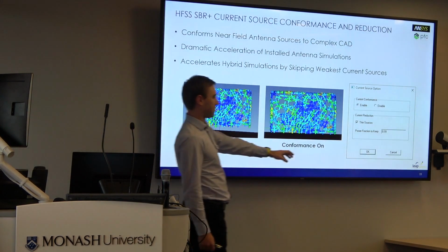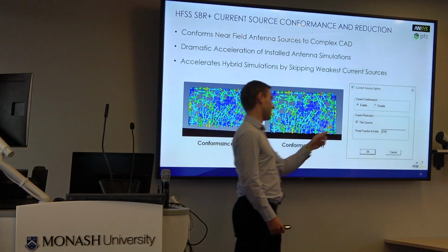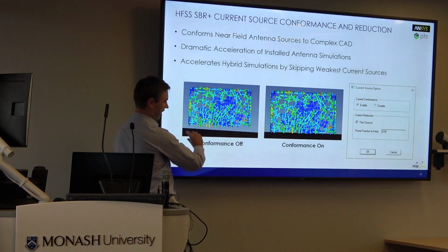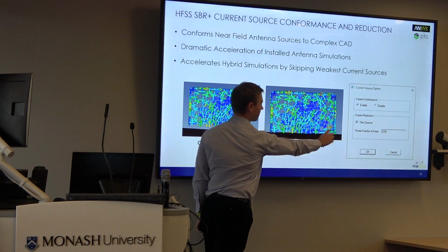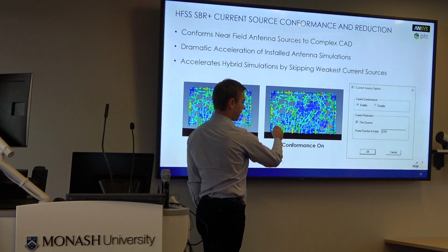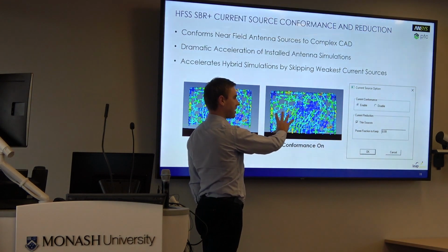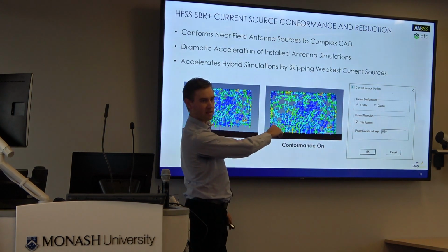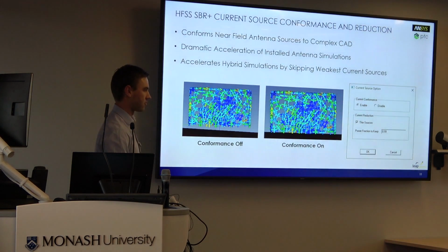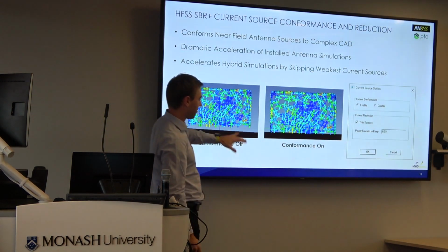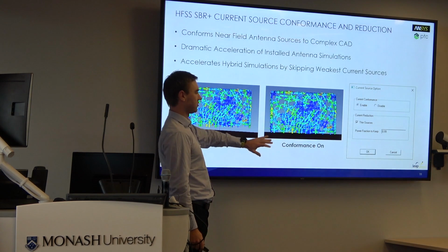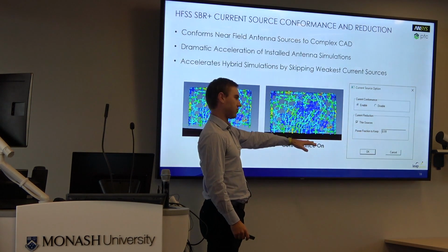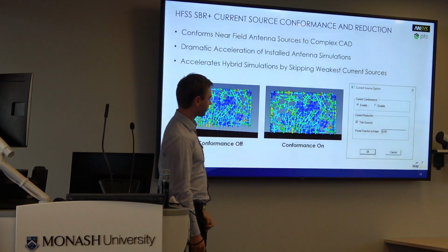Now you have the option to turn on what we call current extrapolation. In essence, there is this gap here. HFSS sees it as a gap, moves along, looks at the top couple of layers of current elements, and extrapolates down to the surface so that you end up with a perfect zero gap here, and you never get that error again. So that's very easy to get sorted. The other thing to be wary of is if you're going to do this with a conducting surface, try and add a ground plane to your original HFSS design to sort out the ground clearance.